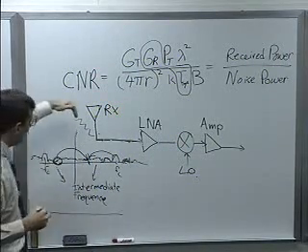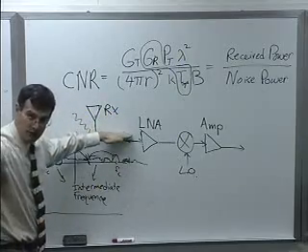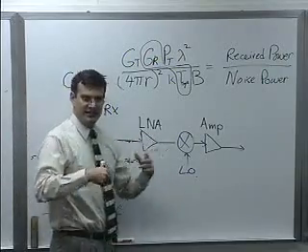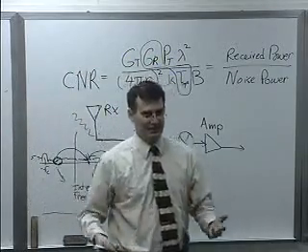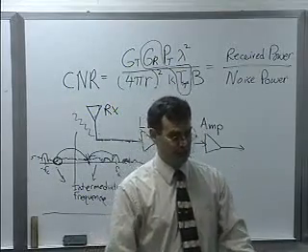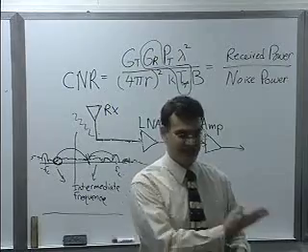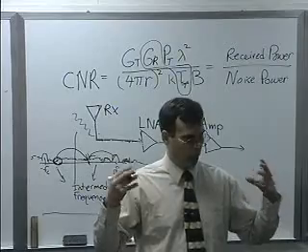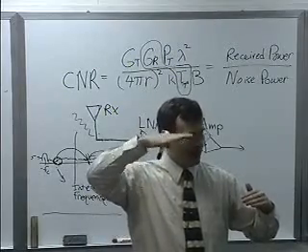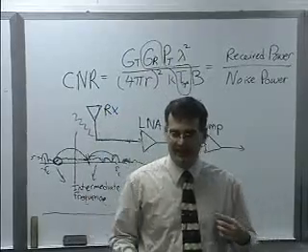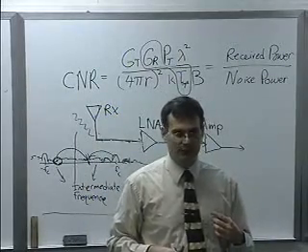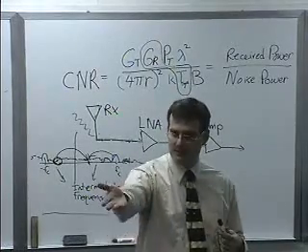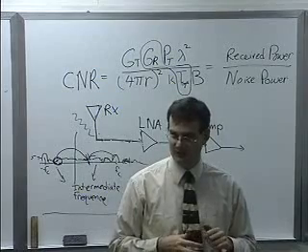Okay, so my signal comes in here. It's got power and it's got noise. And when it enters into the LNA, which is an active device, it's got these biased transistors in it that are being used to amplify the electrical signal coming inside and then leaving. And because it's an active device, and it's got warm components, and it's biased, it's got these junctions that are statistically combining and recombining holes and electrons and all that. I mean, we have a couple of semiconductor guys here that probably deal with this stuff on a regular basis.